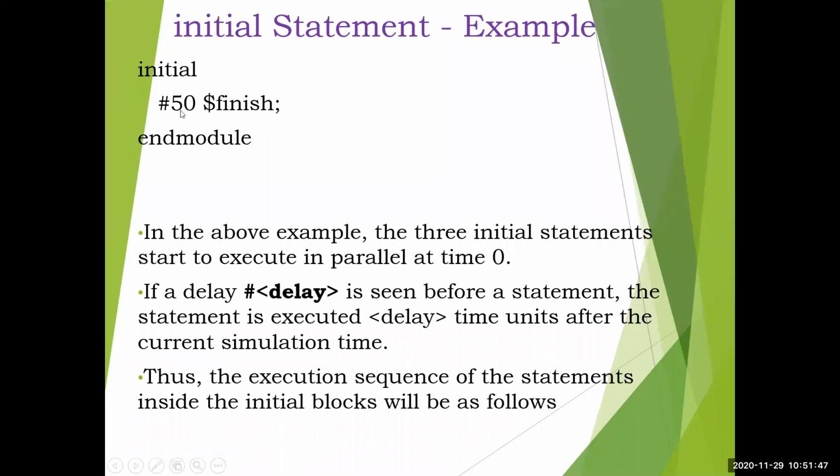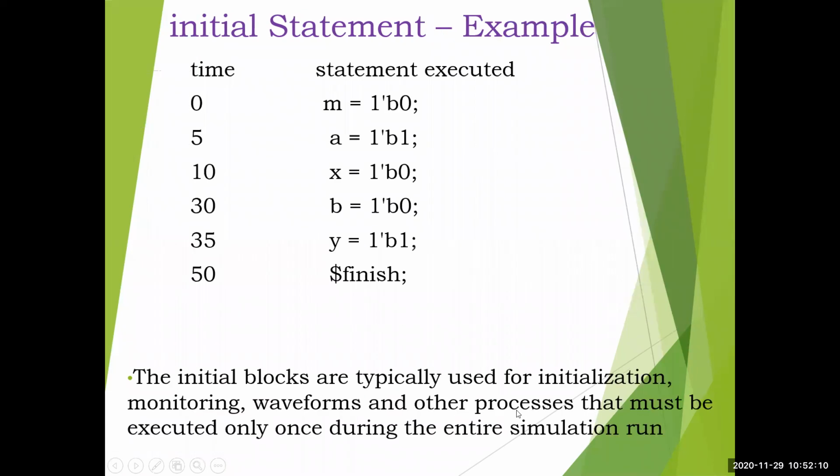So finally, initial #20 $finish. Again here it is a single statement, that's why begin and end are not written. In the example, the 3 initial statements start to execute in parallel at time 0. If a delay is seen before a statement, the statement is executed after that much delay from the current simulation time. That is the delay concept.